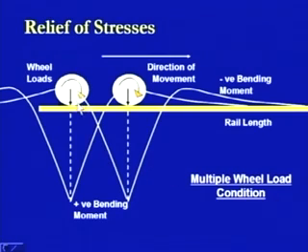One is the load which is coming from the top, and because of this load, the total amount of the bending moment which is being induced, the location of the point of contraflexure at some distance from the application of this load, and then the spacing of these two wheels, because if suppose this wheel is not being placed here and this wheel is being placed somewhere here, then probably because of this expansion of the bending moment diagram which goes something like this, that becomes maximum here and then becomes 0.